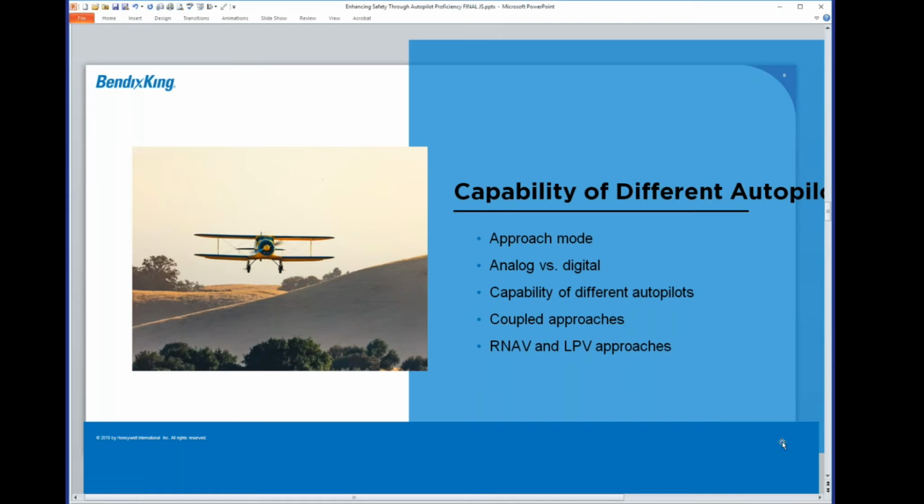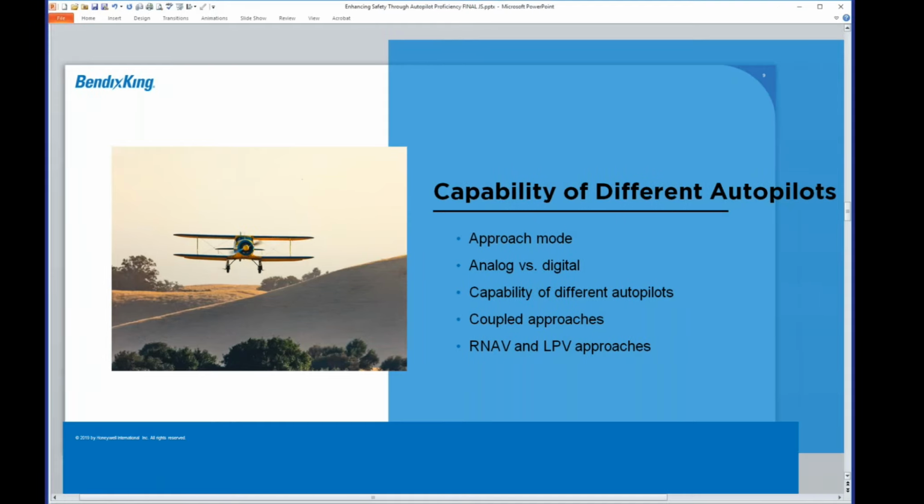And an interesting side note there on GPS steering, we actually find now that some manufacturers of other equipment that we interface with are now taking that heading command and converting it into a GPS steering type command, a commanded bank angle, directly and sending that out to the autopilot. So you actually have the opposite occurring of what used to occur, where everything was converted over to what a deviation would look like on a heading bug. Now we have a heading bug deviation being changed over to look like a bank angle command as we would normally get it out of a GPS, which is actually quite cool.